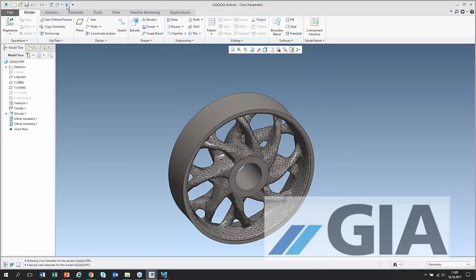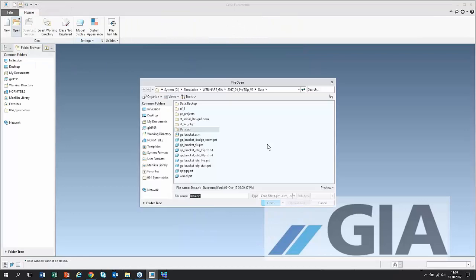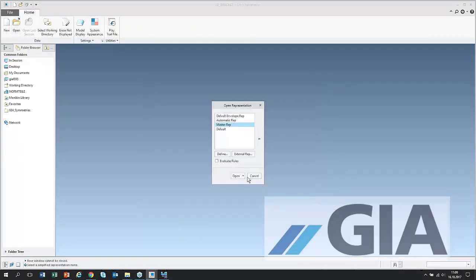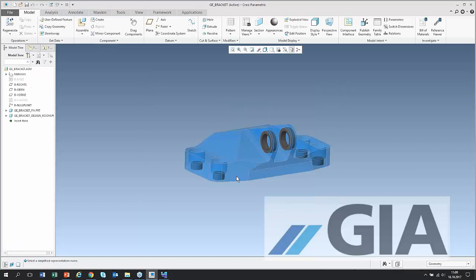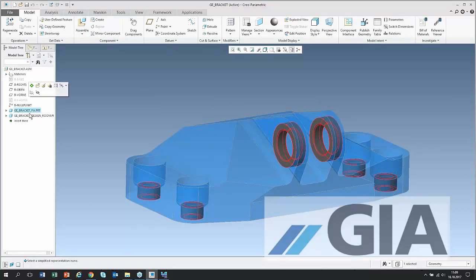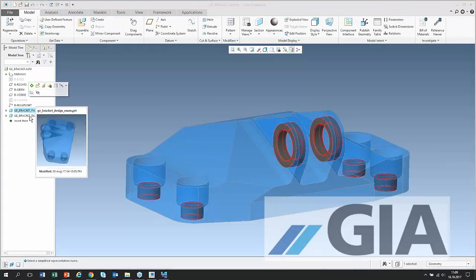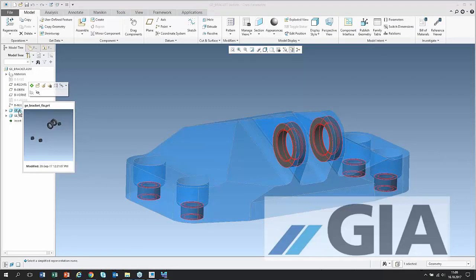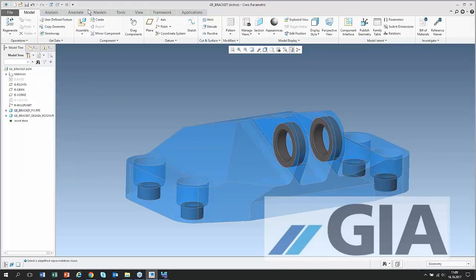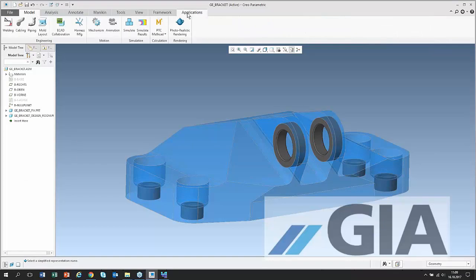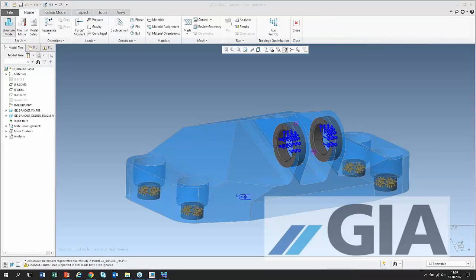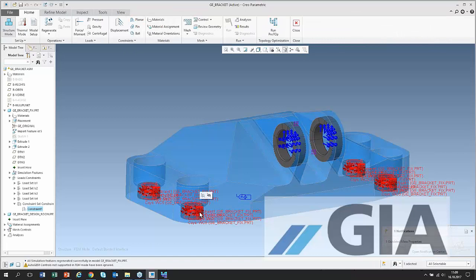Leaving Creo Simulate, closing that window, and now I should be able to open this little assembly. In that assembly I deal here with several parts. So right now the highlighted part, that one, are the fixed regions, and the blue one is the optimized design room. And in Creo Simulate here I set up my constraint data, and I set up here,